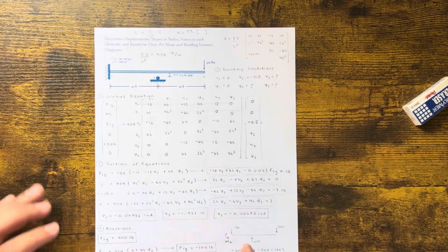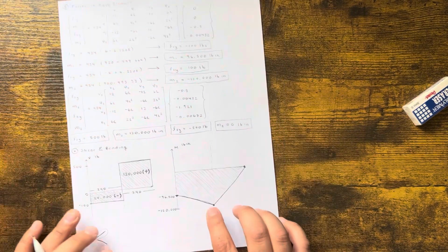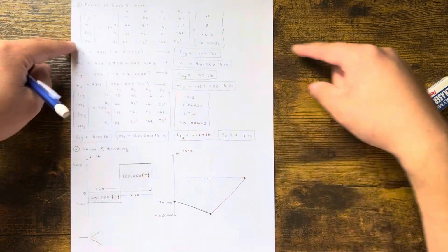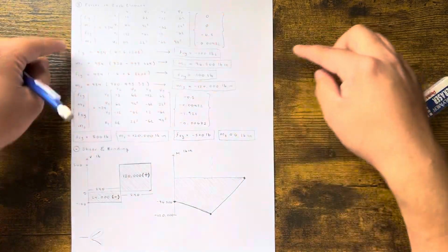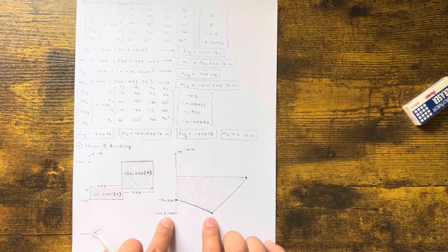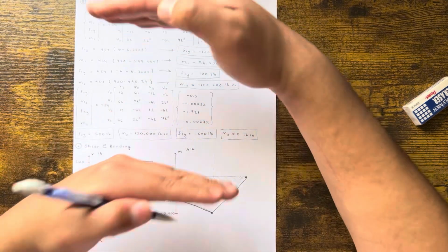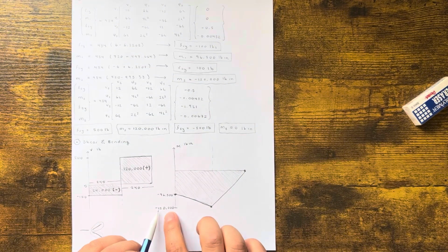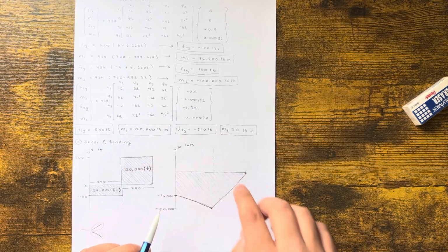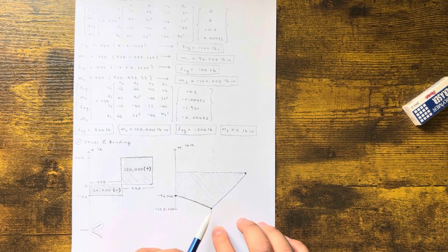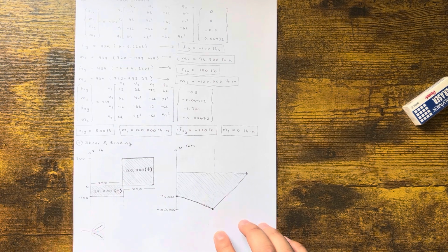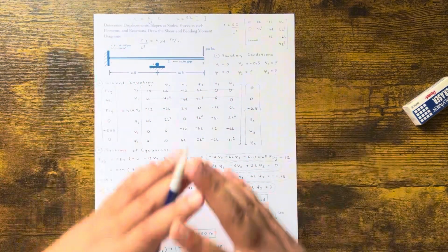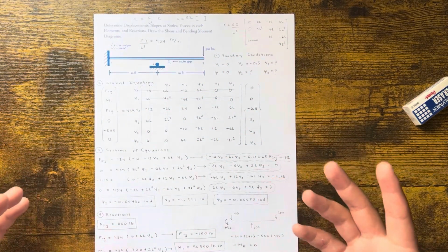Shear, right? The moment is your caps. So in an I-beam, the top flange and the bottom flange, right? An I-beam has two flanges, the top one and the bottom one. 120,000 is resisted by those caps. They're called caps. So you have to design those caps thick enough to withstand 120,000 pound inches. Okay? And as an engineer, you found this number and you found these shear numbers, these critical numbers. You have to design those cross sections. In this case, sounds like they already did. So this problem is more like a check. Hey, let's check if it works kind of thing.